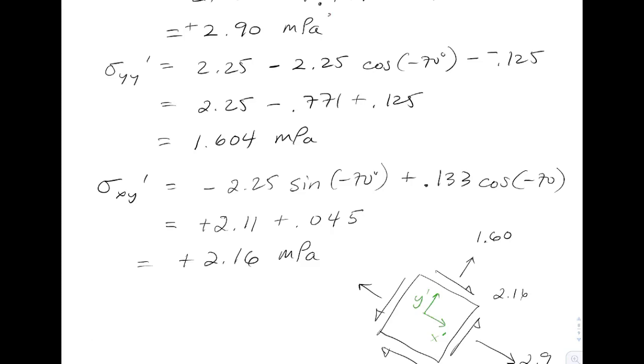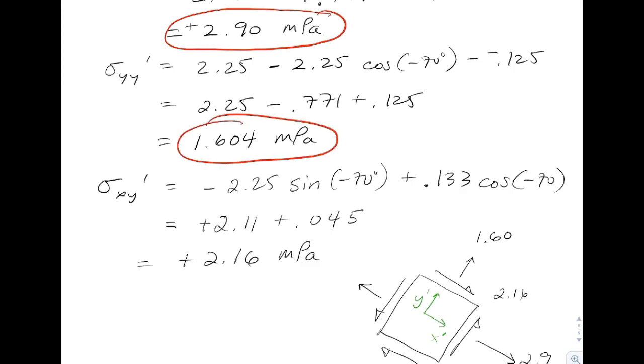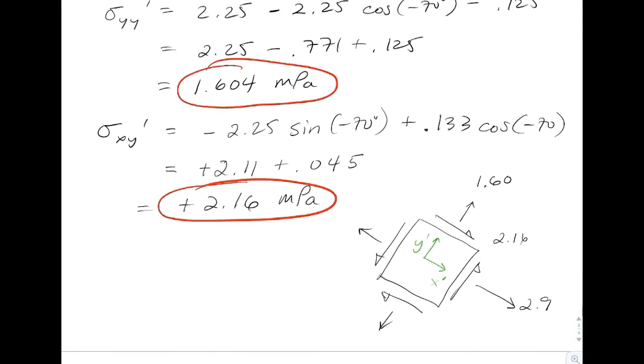We will do one quick one. So there's the x prime stress, there's the y prime, both in tension, and the shear stress. Right? The shear stress is positive, and the way we would do that is on the x prime face, we're going to draw the shear stress in the y prime direction because it's positive. So we end up with exactly the same picture.